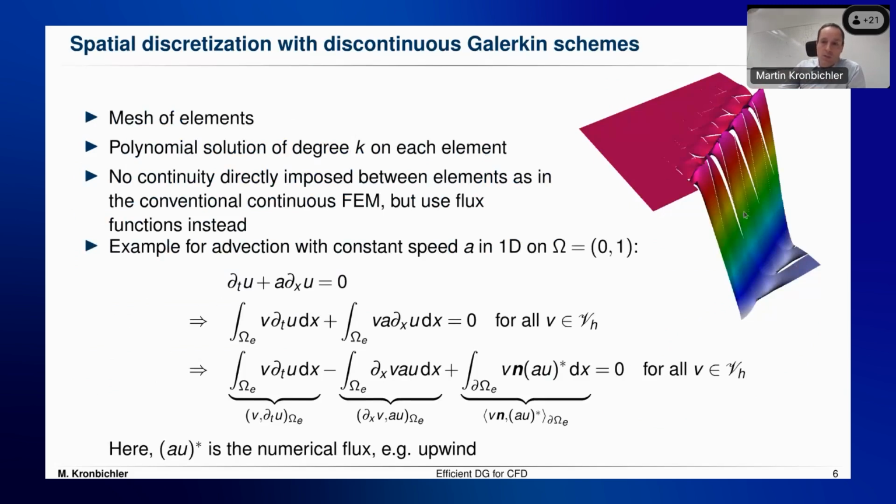So here on the right of my screen, I just inserted a scalar problem, which I visualized. This is a classical transport problem diagonally through the domain. It has a lot of overshoots, so this is not even a perfect discretization for this kind of problem, but I just illustrate the kind of solution fields that you might get with the DG method. When you do DG methods, you use a weak form like the finite element method. So in case we use the transport equation in 1D now, as an example here, we would just integrate over the domain.